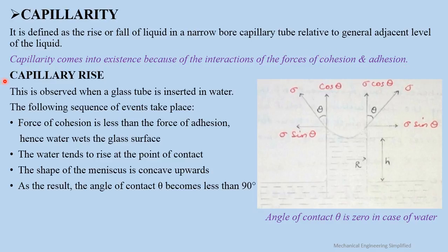Okay. Then there are two phenomena. One is capillary rise, when the liquid inside this capillary tube rises compared to the general adjacent level of the fluid in the container, or it may also fall. So both these cases are considered separately. One is capillary rise. This is observed when a glass tube is inserted in water. When this glass tube, a narrow bore capillary tube, is inserted in liquid, then we experience the phenomenon of capillary rise.